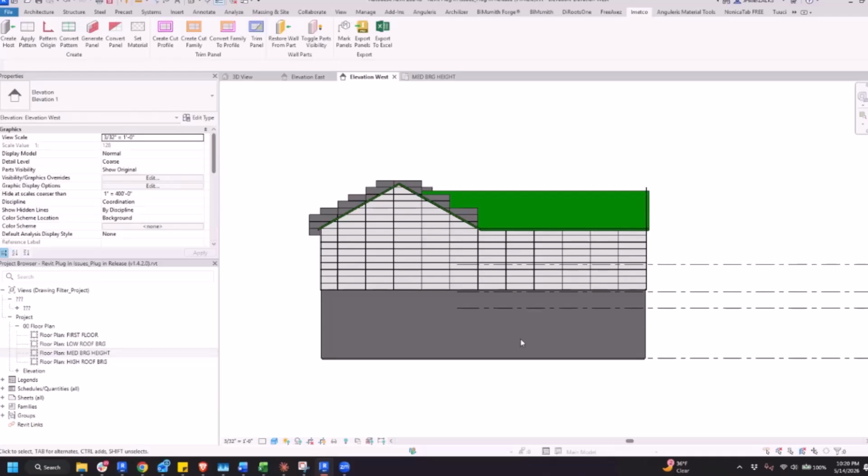This is where you as a designer are going to be able to see things like this. You see the corner on the bottom left, that triangle that you did not notice cut? I accidentally missed a corner right here. So now you have the other tools right here, the convert family to profile. You can hover over your void and it's going to reconvert it into lines.